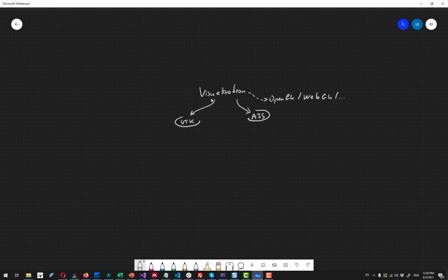So why and when would I use OpenCascade visualization myself? I would prefer AIS visualization whenever my concern is performance. For example, if I had a huge CAD assembly, then I would definitely stick to this approach, because it has a really nice performance, especially for huge assemblies, and especially if you use it correctly, like if you use a different instancing mechanism, which are also provided in frames of the AIS architecture. This is one thing. And when I would use AIS, when I am not going to customize it, like let's say no customization.